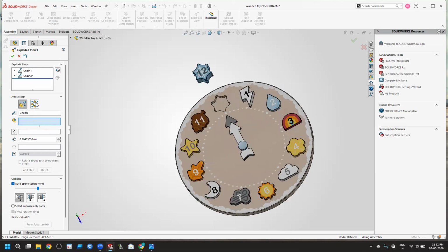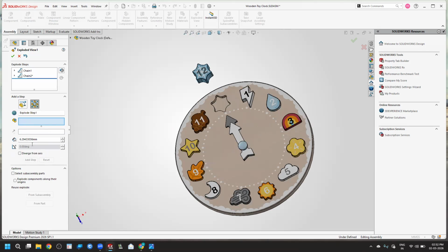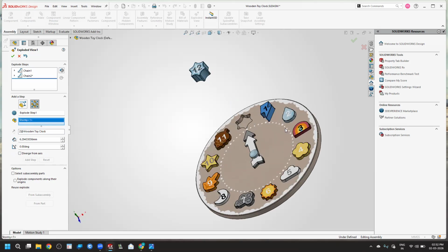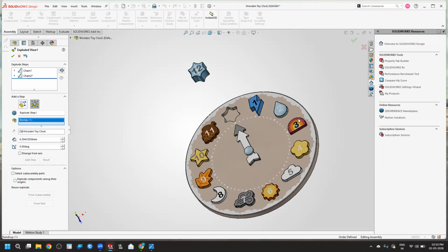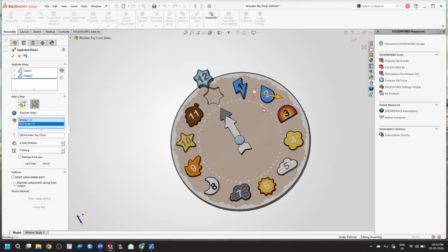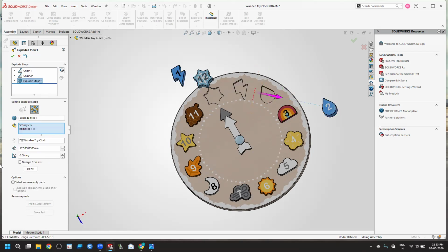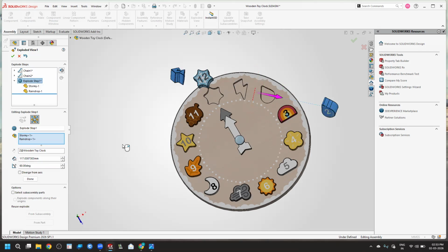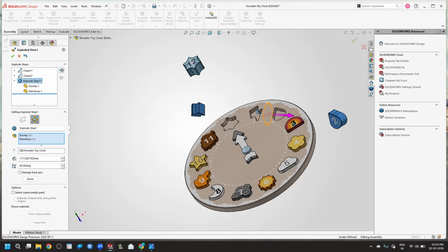After that, if you wanted to use the radial step, you only use the radial step when selecting two objects. Unlike the regular step, you need two objects for the radial step to be active. In the radial step, unlike the regular step, the two objects you selected will move in the opposite direction, or they will rotate in the opposite direction. Here I'm putting 60 degrees to show you how it rotates in the opposite direction.